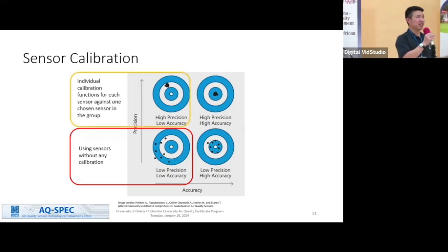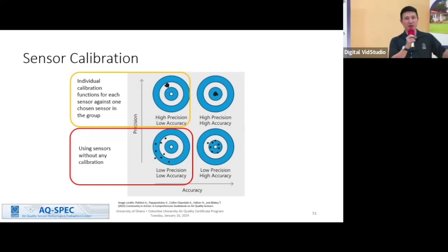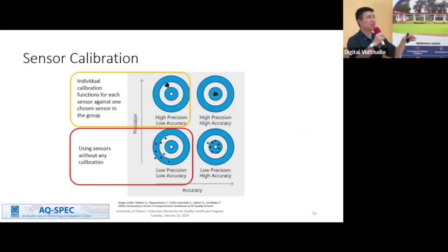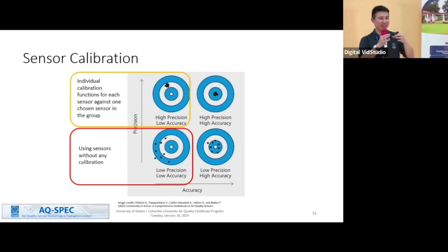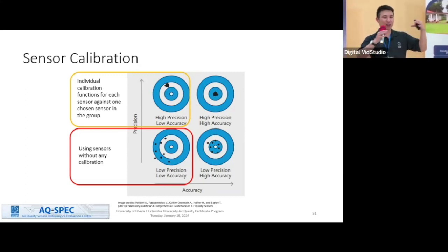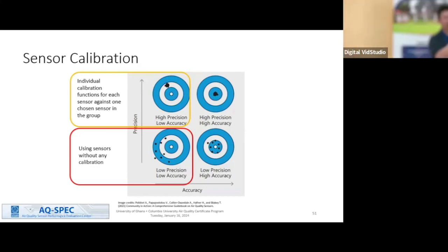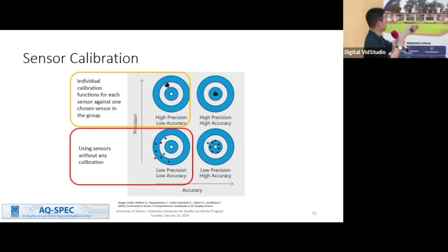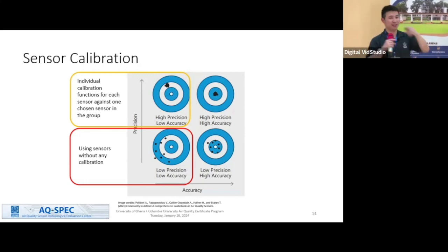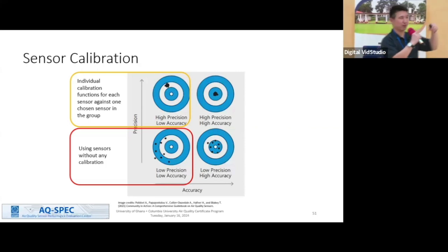And then this is a less worst case. Maybe you choose a golden sensor. If you don't have access to a reference monitor, you choose a golden sensor and then you adjust all the other sensors, you calibrate them to the golden sensor. So even though they may all be wrong on a quantitative level, at least they're all close to each other, like they're all responding the same now after calibrating to the golden sensor, so you can draw qualitative conclusions. You can identify a hotspot. So if two sensors are now doing this, at least the difference in their response is meaningful. Whereas if you didn't do the calibration, if you're in the danger zone, you can't draw any conclusion from their different responses.